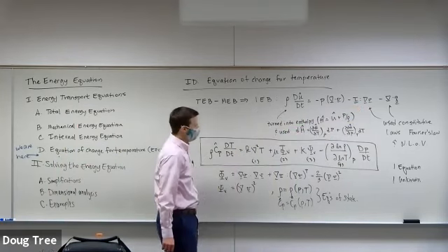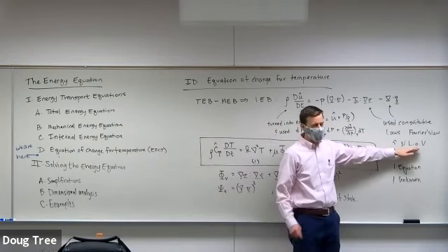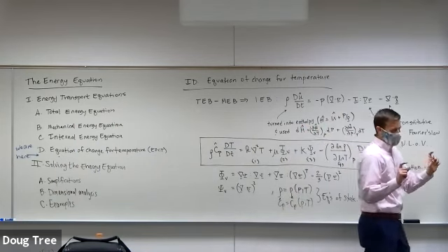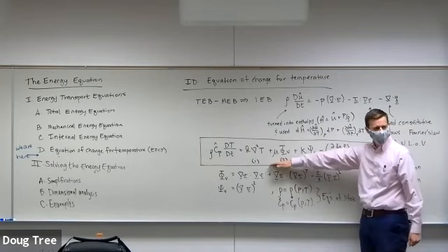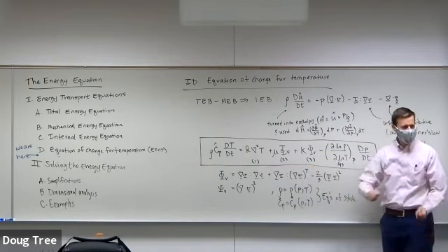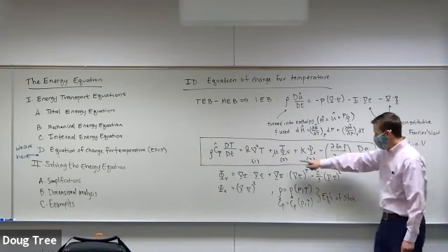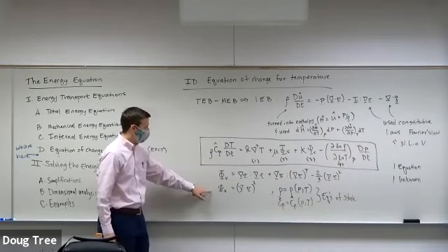If you remember Newton's law of viscosity for the tau, there were two viscosities. There's our regular normal shear viscosity that we're used to, and then there was a dilatational or volume viscosity. And that's what leads to these two terms. Mu has the shear terms, and kappa has the volume expansion terms. Here you can see you write out this capital phi and capital psi.